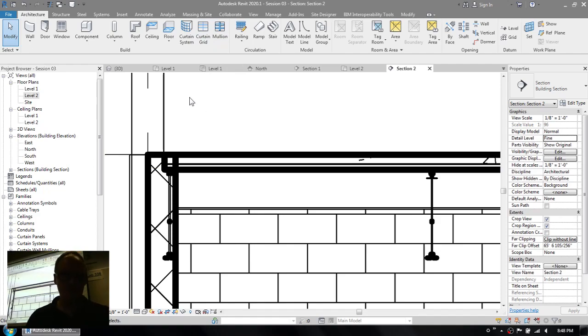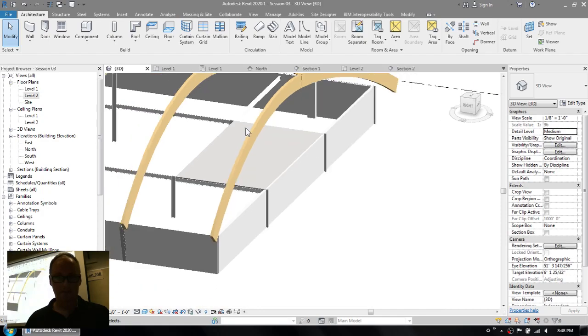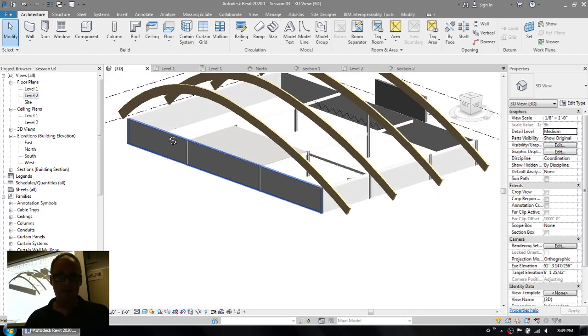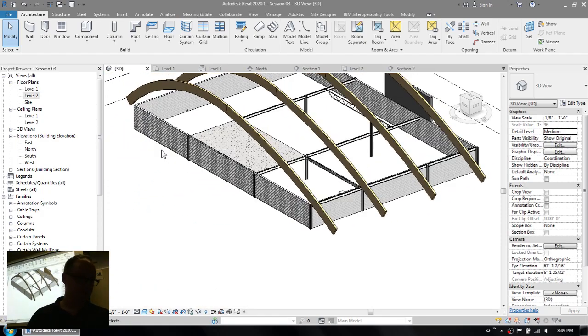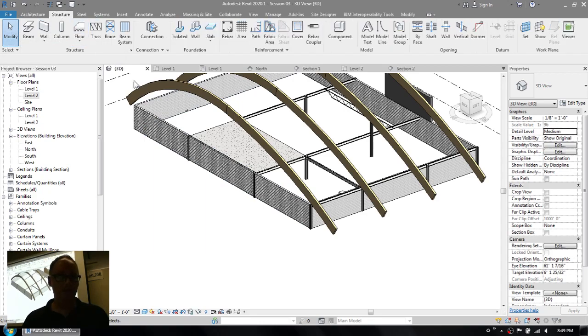We're going to move on to foundations. We're going to look at two foundations, really, the two styles of foundations, wall foundations and isolated. So first of all, isolated, that's really code for pad footing. So an isolated footing is just a pad footing. So to get at this stuff, you go to the Structure tab. There's your isolated footing tool.